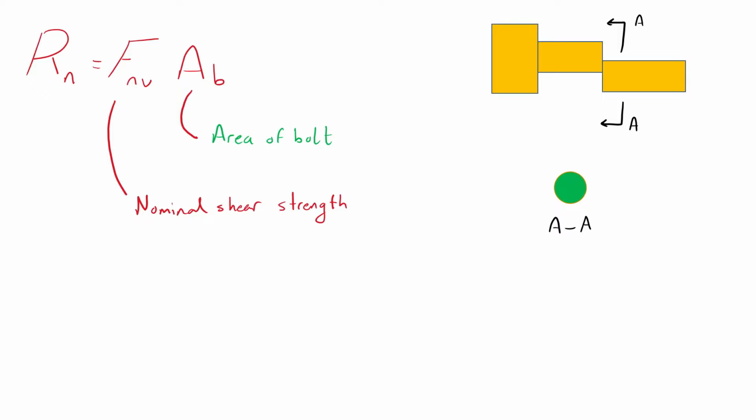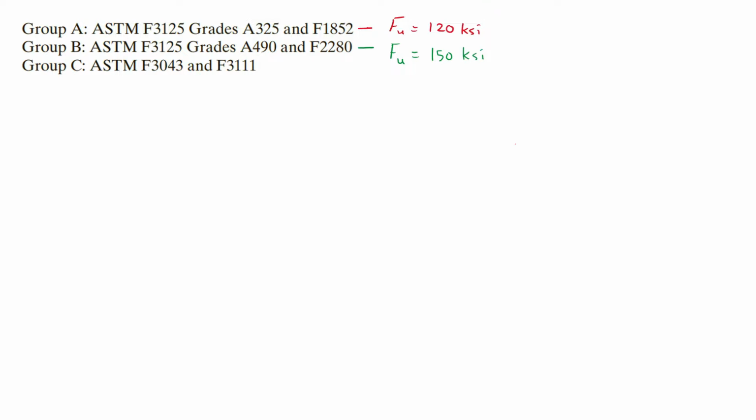Structural bolts are available in two general categories: common bolts, also known as unfinished bolts, and high-strength bolts. Only high-strength bolts can be tightened to produce a predictable tension in the bolt which can be relied on to produce a calculable clamping force. A490 bolts have a higher ultimate tensile strength than A325 bolts and are assigned a higher nominal strength. They were introduced long after A325 bolts had been in general use, primarily for use with high-strength steels.